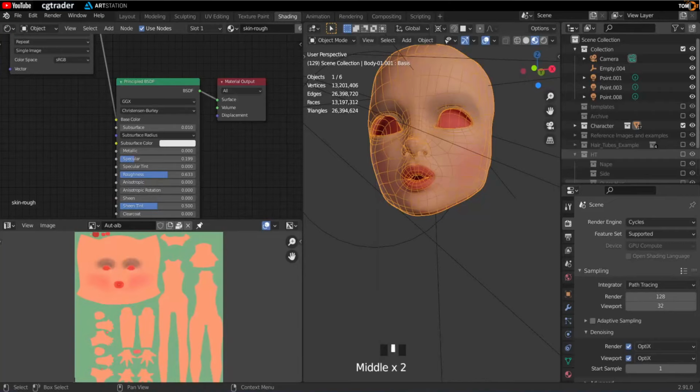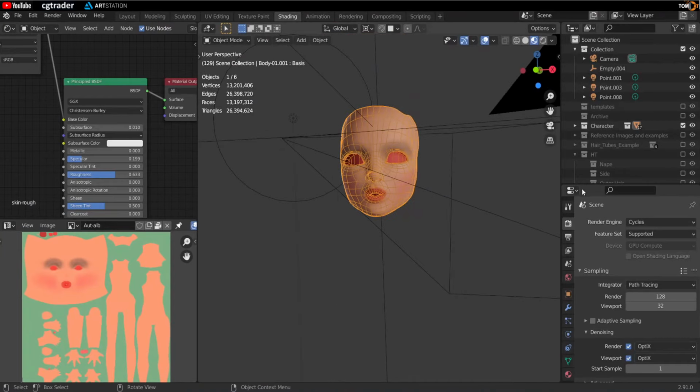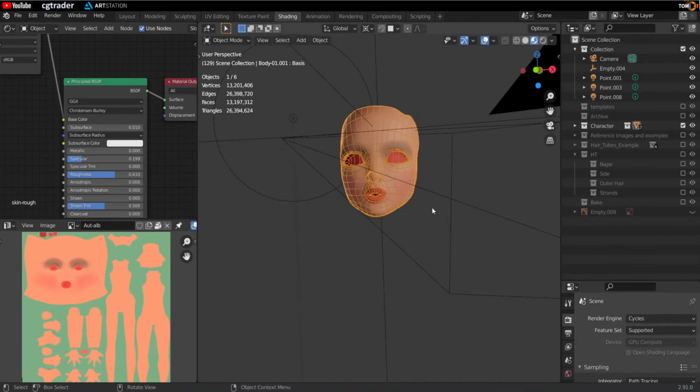Okay, let's go to our shader workspace. So when we bake the normals, we want to have our high res mesh, the low res mesh, and we want to create a new texture that's inside our low res mesh. When we bake the normals from the high res mesh onto the low res mesh, we actually record it in that new texture we're going to create that's inside the low res mesh. So let's go and create that. Let's make a little more space here, and let's get this file set up to bake.